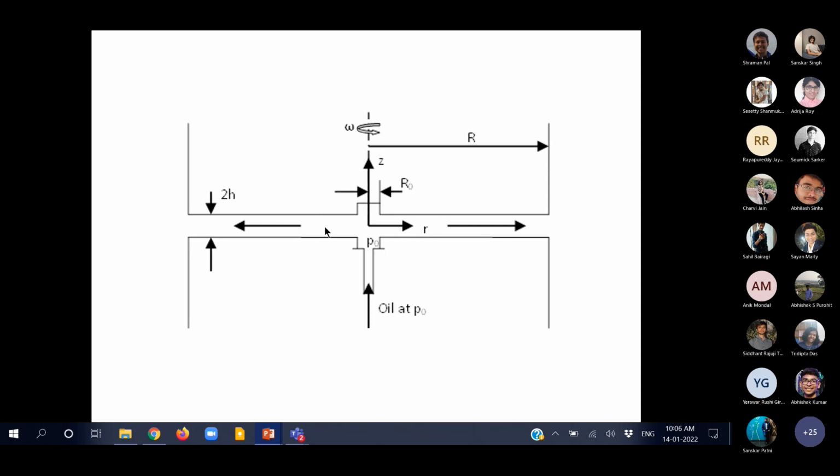As the gap here is very small, the liquid layers are going to move past one another with a very high speed. That means the velocity gradient in this case is going to be tremendous. Once that happens, something similar to solid friction, when a solid block is pulled at a high speed over another solid block, there's going to be a dissipation of energy, and that dissipation will manifest itself as an increase in temperature between the two surfaces.